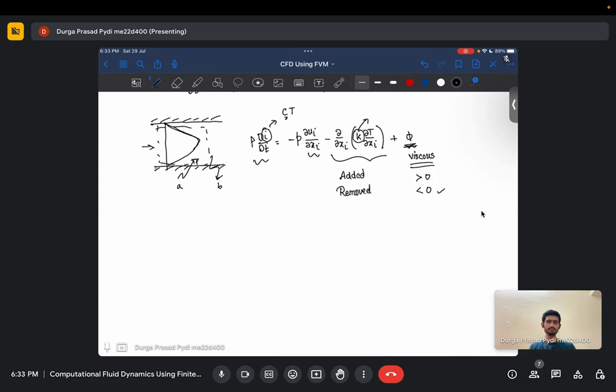because the complete velocity profile will be developed after the hydrodynamic length. It is loss of internal energy, or loss of velocity, that gets converted into this. Essentially, when a fluid just touches a solid, because of the no slip condition, there used to be some velocity which is now getting converted to zero, so some energy has to be lost.